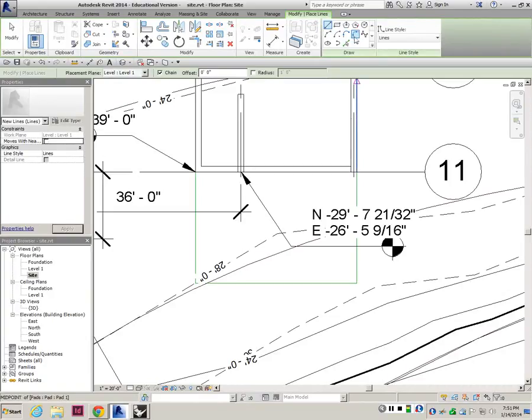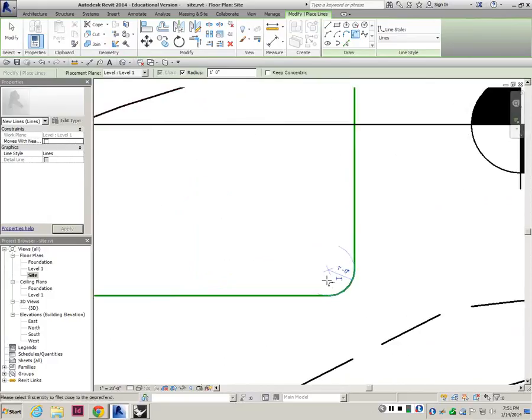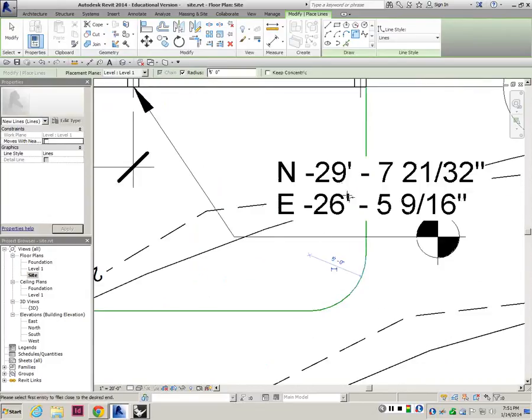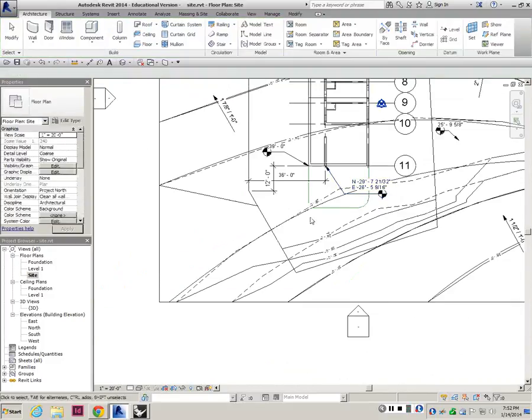We want to round the corner of two intersecting lines. So I select that one and type in a radius. I select this one, and it put it directly as 1, but let's do maybe 5. This one and this one. That will be a fillet. So I'm done with that one.